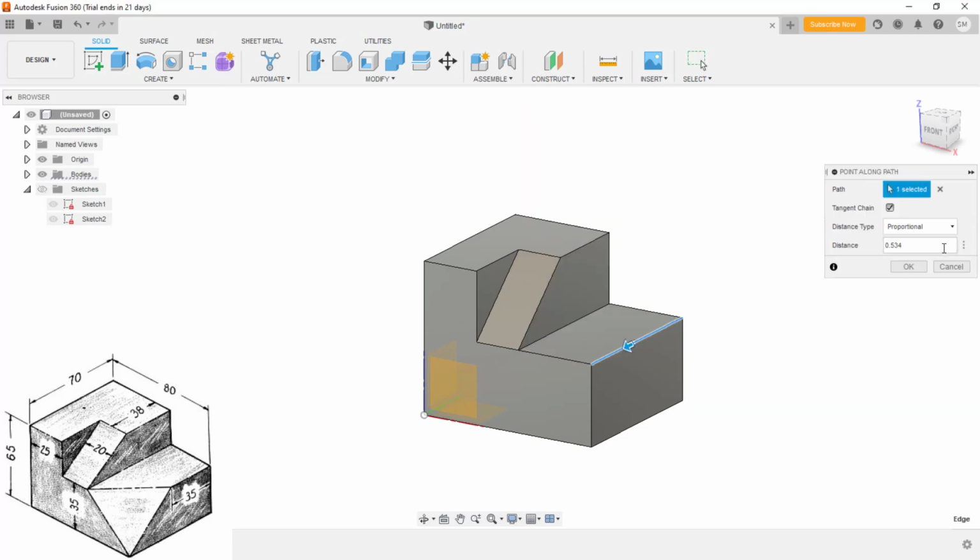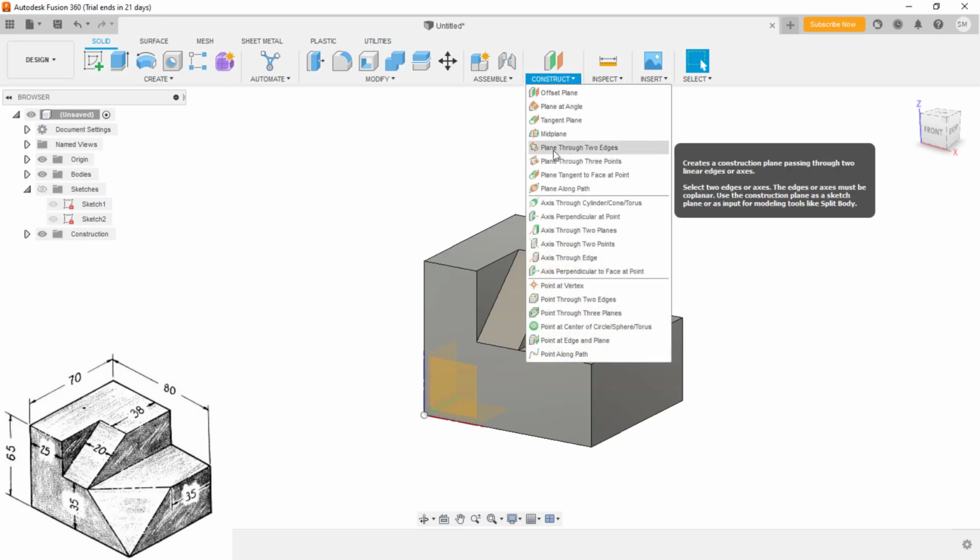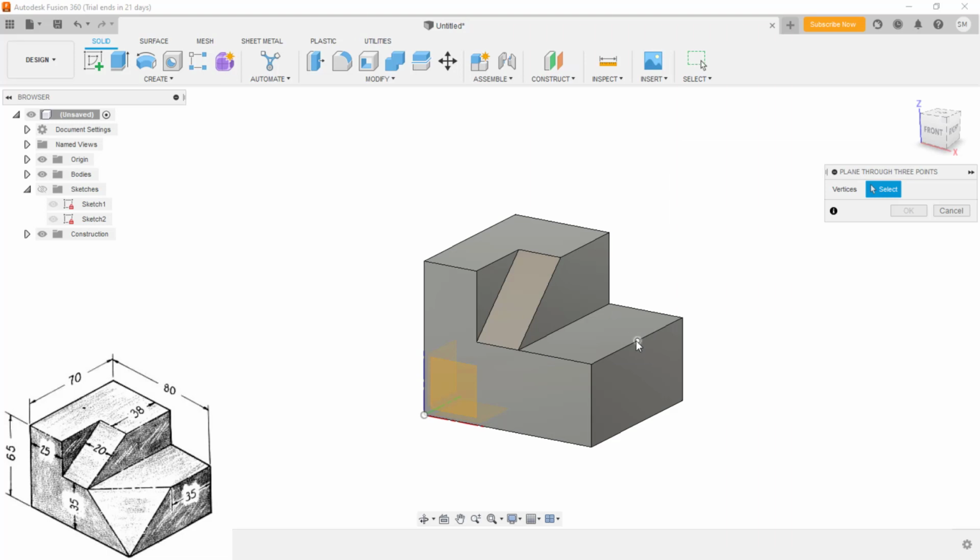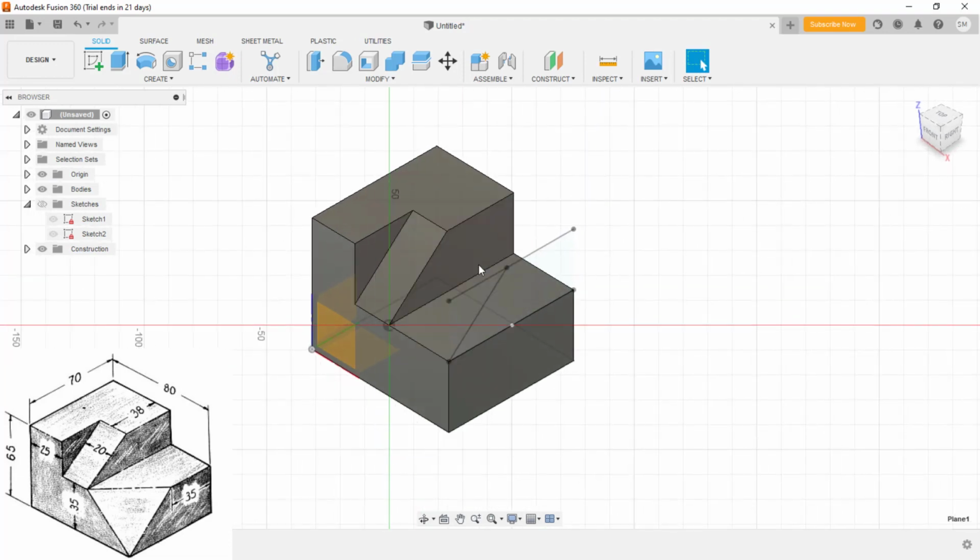So next thing is I need to create the 3 points. Here I'll add the point first, so you can define the location. It is proportional. I'll activate the physical and add the value as 35. Overall is 70, and it is exactly at the center. Now I'll go again with the constraints. I'll add the 3-point plane. So I'll select these three locations, and on it I'll sketch, right click and create sketch.